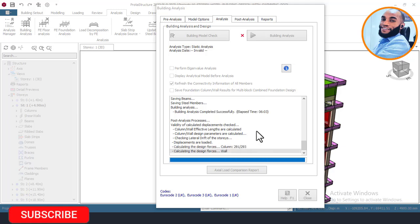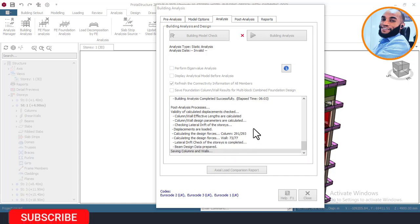Then we will now enter into the design stage, which will not take much time, although it can take up to 16 minutes to perform the design, because it will have to design for the beams, and if there is any reinforcement that is failing, or that is not sufficient, it will just use the next bar, which you provided. Don't forget that we provided 16 millimeter diameter for our beam reinforcement as the minimum and a maximum of 25. So if 16 is not sufficient, it will pick 20 and then 25, okay, and so on.